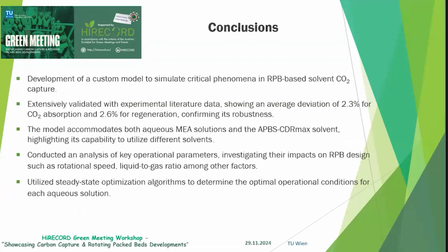To conclude, we have developed a custom model to simulate all the phenomena that occur inside these 2 reactors for a solvent-based CO2 capture process. We have validated it with experimental data, which makes the model reliable and effective. We have also integrated MEA solution and CDR max solvent, which is part of the scope of this project, highlighting the ability to use different solvents.